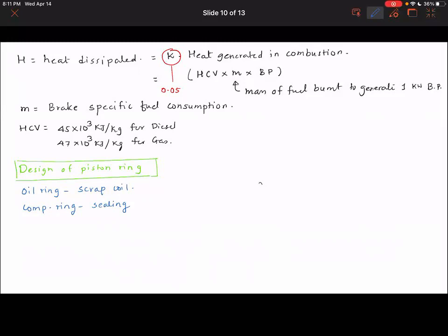When you are putting the ring inside the piston, you slide it, and when you drop the piston in the cylinder assembly, you have a special tool that compresses the ring, and then you slide the piston inside the cylinder to make sure that the contact and the assembly are proper.